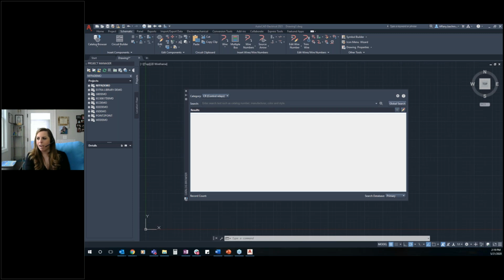Okay. And then another one from Mark here. Is there a way to export the template paths and block file paths and save them or send to a new user so they can import the same file paths that they should have during setup? That is a very interesting question, and I would love to unpack that because it talks a lot about implementation of the software. Yes, there is a way to share that out. That's your environment file. If you edit all of those paths and get them set up the way you want, you can share your environment file with other users to ensure that everyone is using the same environment file that's going to take things to the right paths.